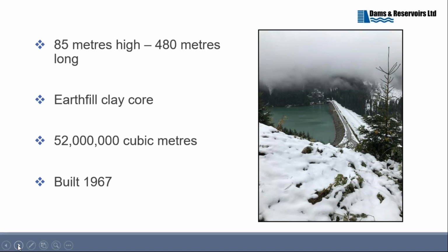But you can see here that the dam sits on a significant amount of alluvium, and in fact there is not a complete cutoff. And when they briefed me about this particular dam, they told me that within this significant depth of alluvial material in the bottom of the valley, there is a silt layer, which is not continuous because we drilled lots of holes into it, but it is that silt layer which ensures the water tightness of the dam, although it operates as a steady seepage dam with flow taking place below the dam almost on a continuous basis.